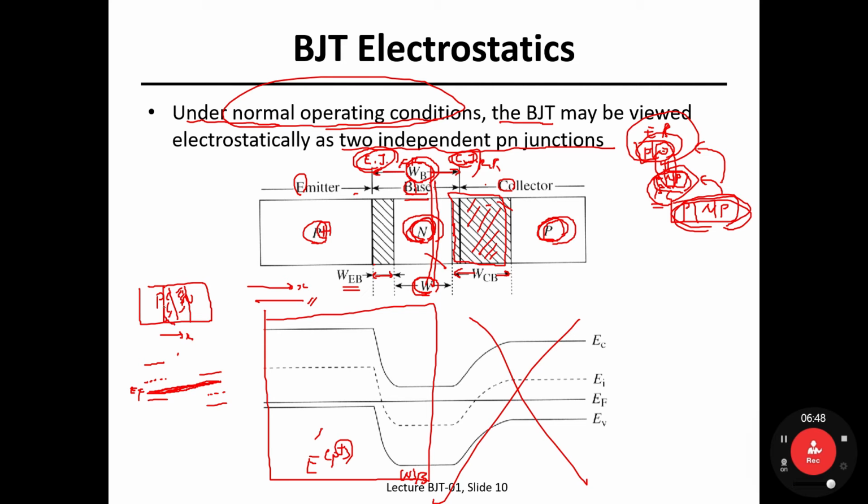On the P side you can see the band bending from upside to downside, and the energy band diagram's band bending can be found inside the depletion layer from upside to downward, up to downward direction. So this parabolic curvature can be well drawn when the P side and N side doping concentrations are comparable to each other.